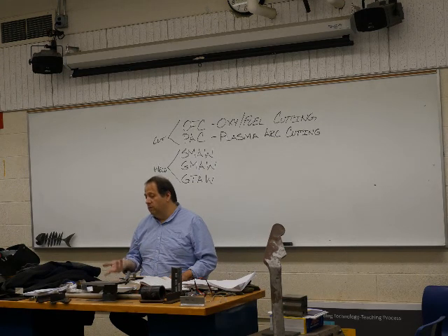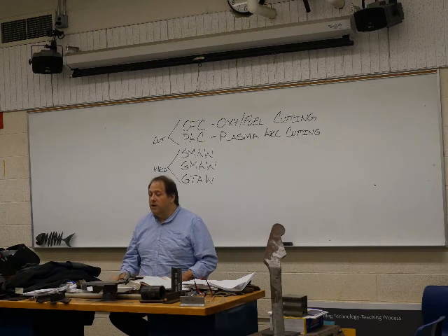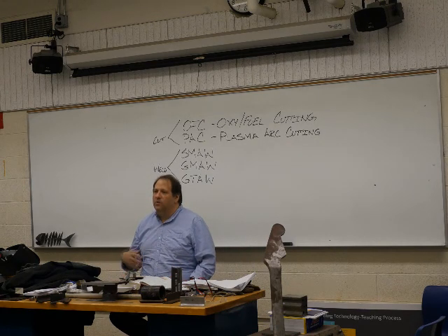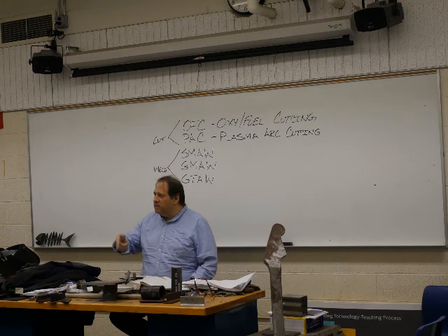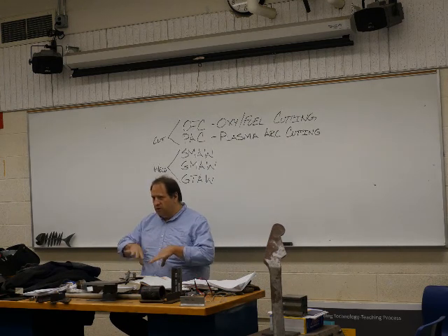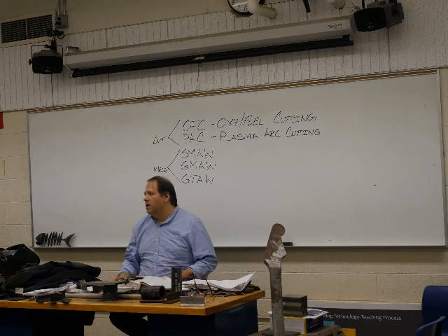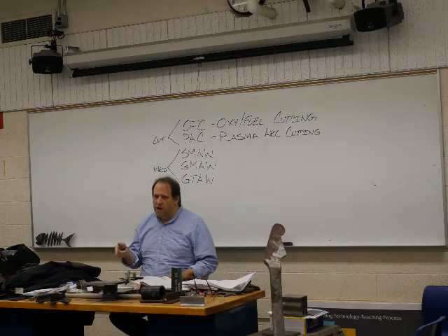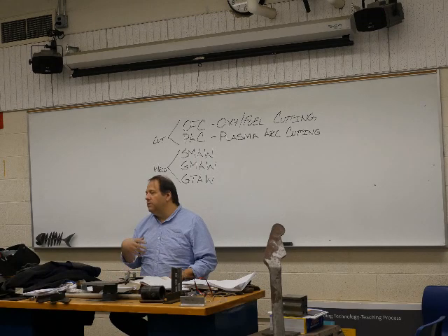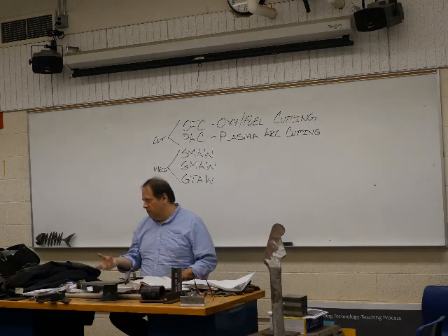So we already know what the melting temperature of steel is. We're way, way above this. So in this case, this is a melting process, but it melts at such a high rate at 20,000 degrees that you get a nice clean cut. And it's not going to spread the heat all that much. It's going to be super concentrated in one little area. So our curves are actually going to be nice and tight. There's limitations on both systems, okay?